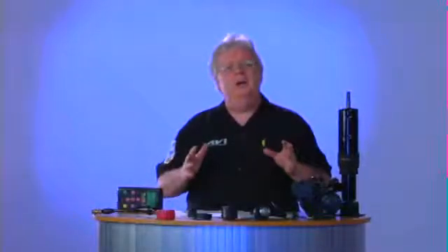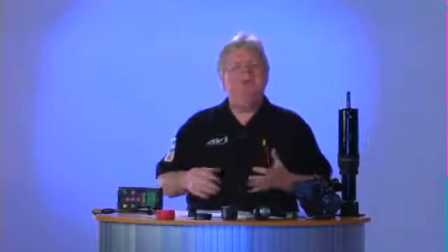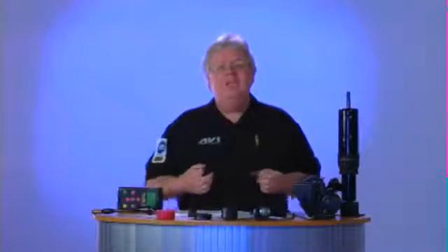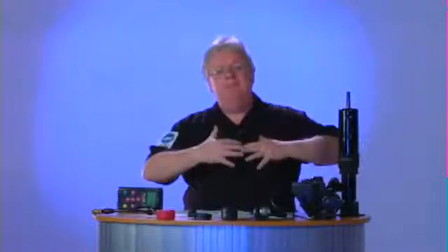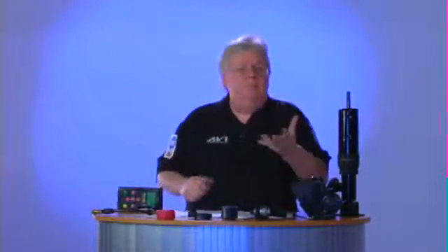Not everything is in a fog of high-tech mumbo-jumbo with black smoke and modules. There are a lot of things. In fact, the majority of car repair is a common sense approach to the fundamentals of mechanical things. So if we think about stiff suspension, or stiff steering I should say, we have a possible cause of being dry, lacking lubrication. So that makes sense.